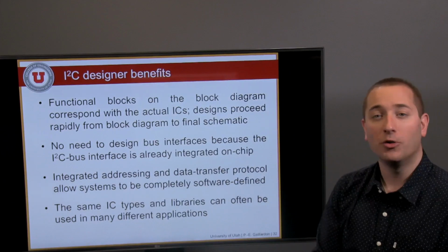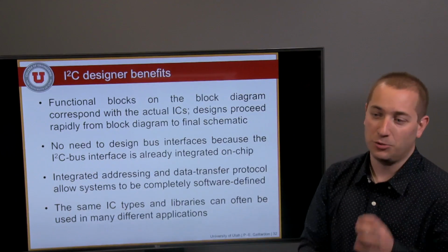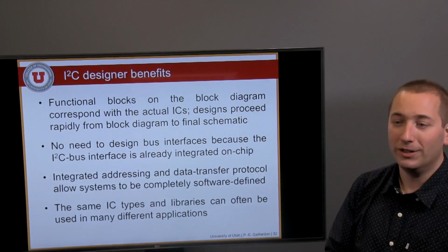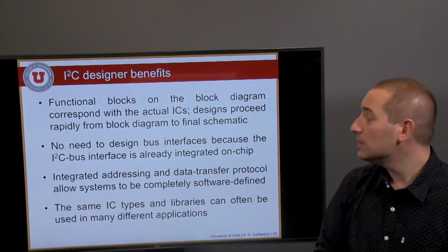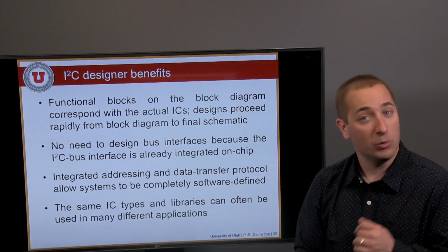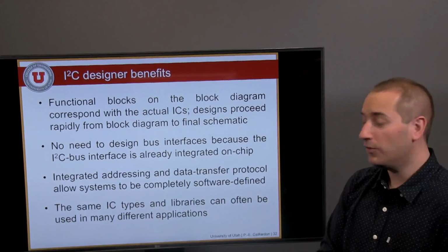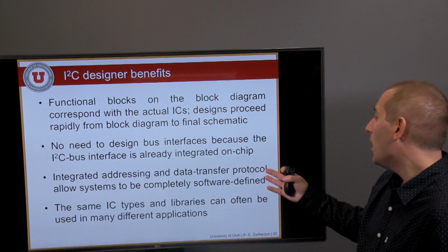If, for example, you want a temperature sensor, you will have a temperature sensor as a clear IC package, and you only need to write a very specific driver for that. You don't need to design specific bus interfaces. Everything will follow the standardized I2C bus interface, all integrated on your chips.